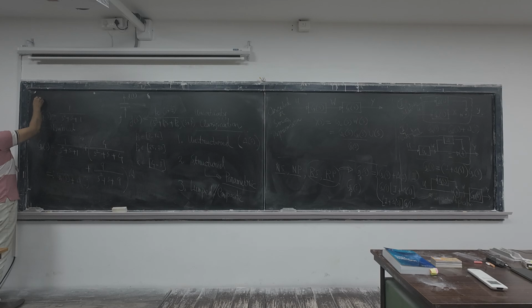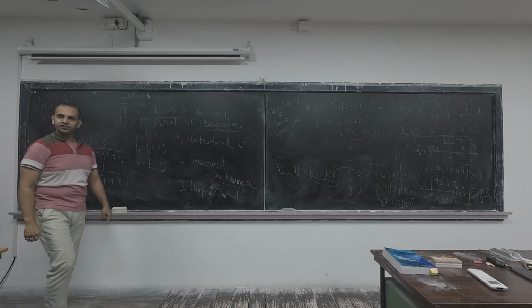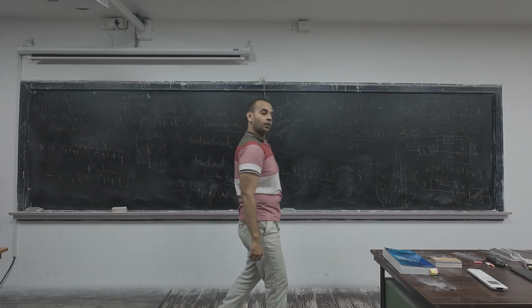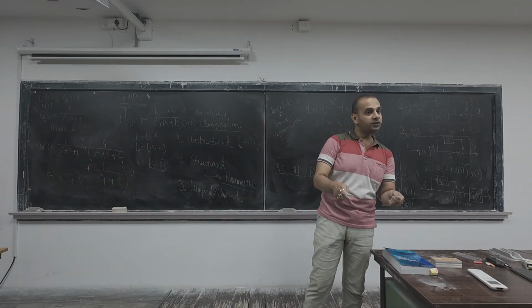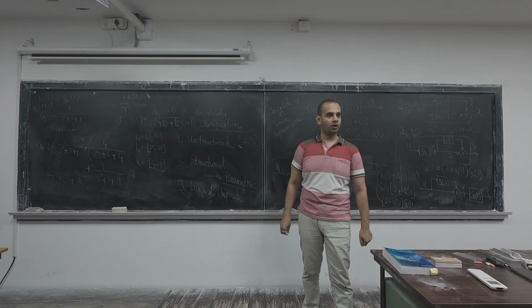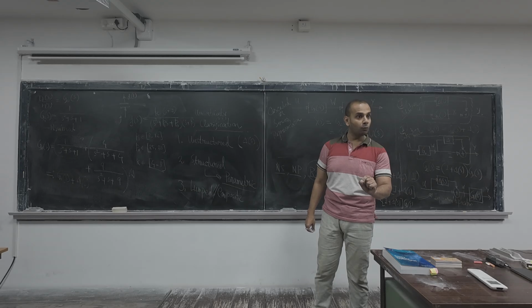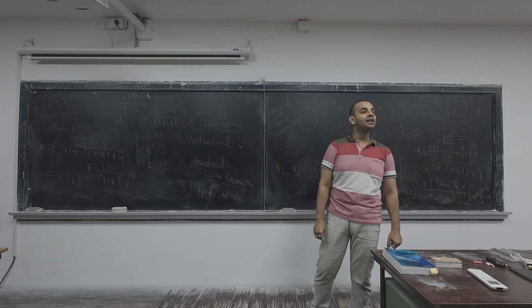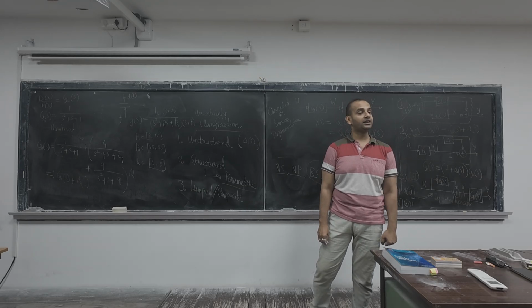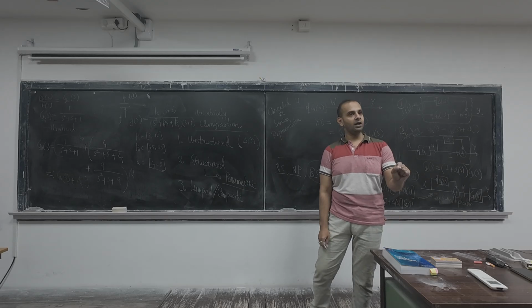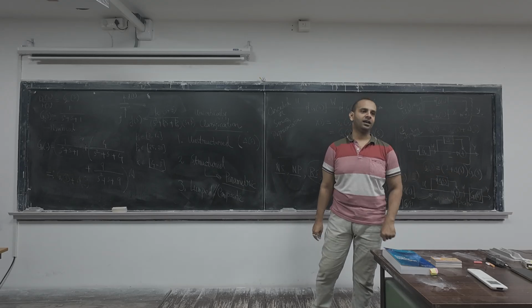Suppose this is d1, then capital D1 of S by F of S is actually my G delta of S. Now, why unstructured? Because it depends upon the experimental procedure you carry out. Whether you will get 5 extra modes, 10 extra modes, or 50 extra modes depends completely on how perfectionist the person is.